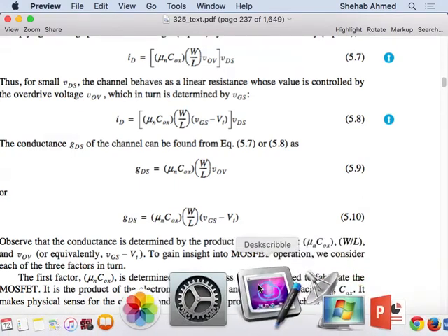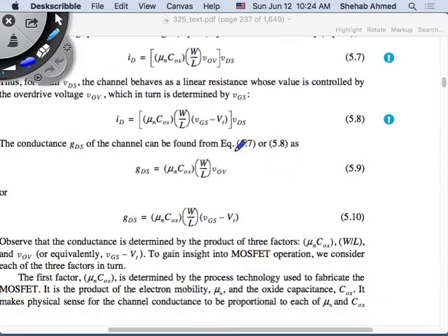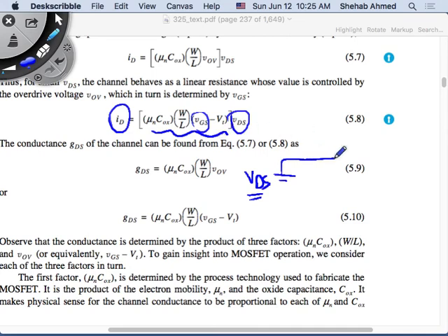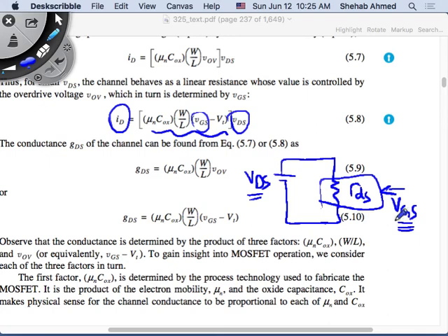You're controlling the value of the resistance between the drain and source. Just think of it simplistically as having drain current and source voltage flowing. This is your VDS voltage that you applied later. First we had VGS. VGS is what's controlling this value of resistance, RDS. Can you imagine this? So I'm applying a VGS to create a resistance of some sort.